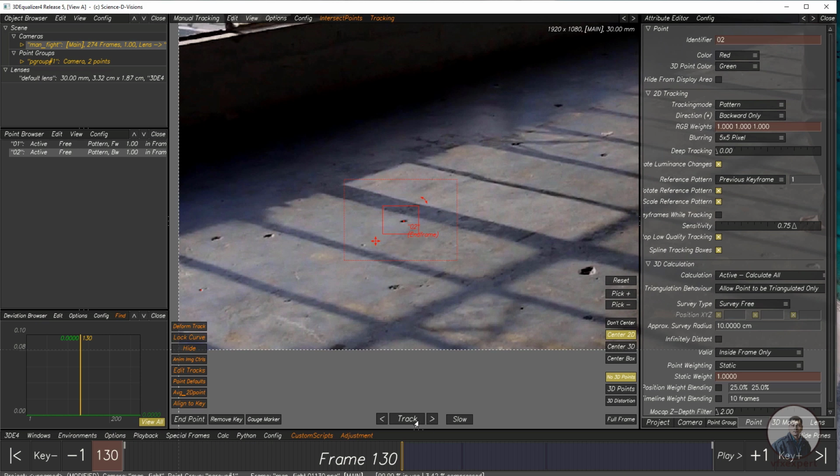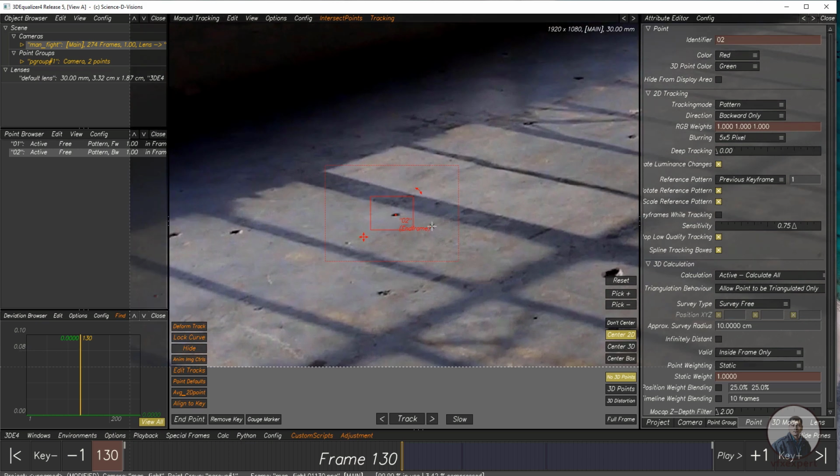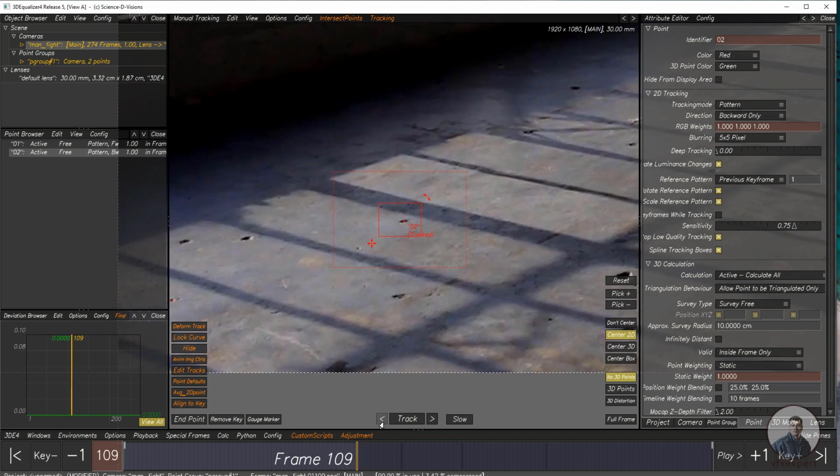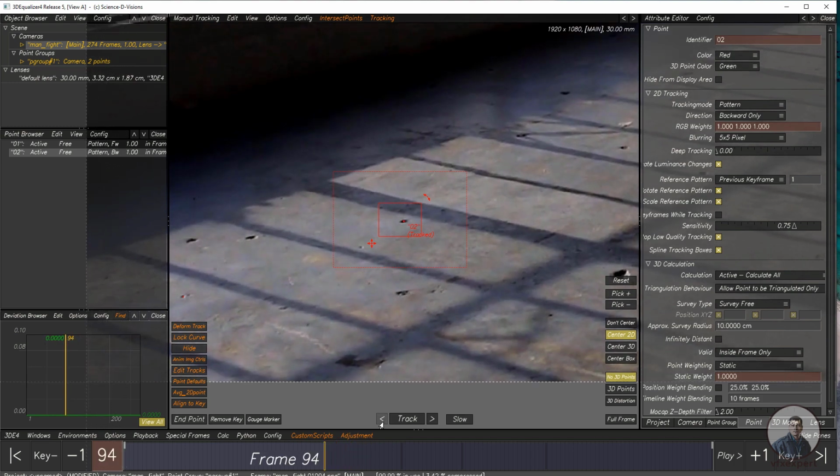Now if you are going to track, it will not track here, because you will get this end frame option. So we have to enable this again. For this, simply click on this end points here. Now I am getting this key frame here, then easily you can track backward. You can click on these options, or track frame by frame. This totally depends on you.